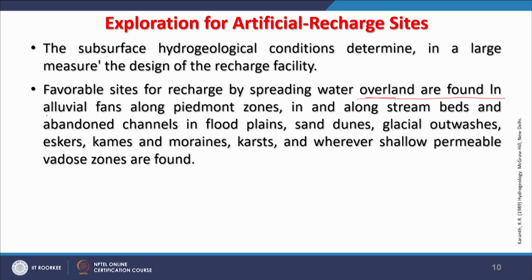Overland are found in alluvial fans along piedmont zones. So, depending on hydrogeological conditions and subsurface geology, appropriate measures, whether we should go for surface groundwater recharge structures or subsurface, will depend. So, in the case of alluvial fans, spreading water and allowing water to remain for some time on the surface will recharge the groundwater regime, because that is the alluvial part. And along stream beds and abandoned channels in floodplains, that is another very good area, because abandoned channels are nothing but alluvial.